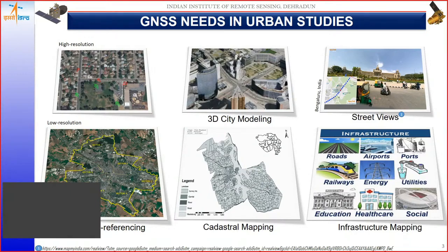You can also consider the ownership details, because those are also very important. The typical cadastral maps, which are typically available at 1:4000 scale and which have some primitive kind of projection system, using the GCPs or ground control points acquired using the GNSS systems, these cadastral maps and their parcel boundaries can be fetched, and then they can be overlaid on the satellite data to see the details, and then other mapping applications can be conducted.